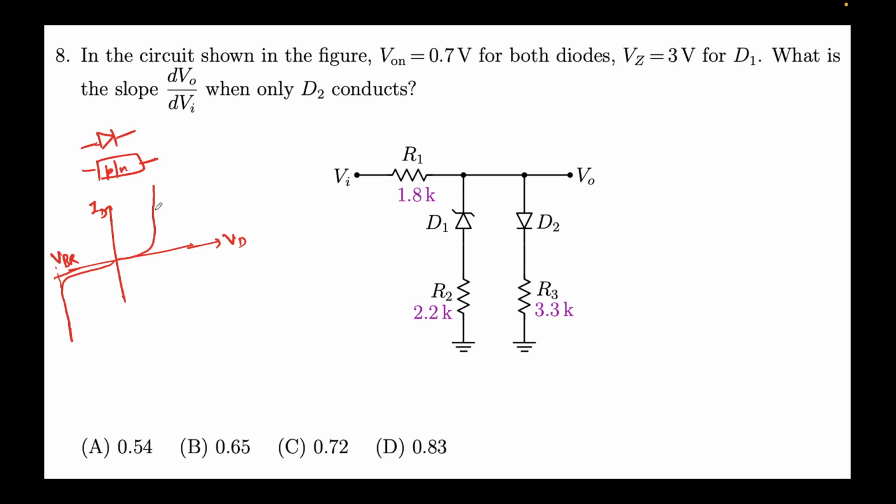And if we take a derivative of this, you can find something called V on, which we are assuming for silicon diodes to be 0.7 volts, right? So when you operate a diode in this region beyond breakdown, this diode is no longer useful. If the breakdown is avalanche type, this diode is useless. However, there are certain diodes based on doping that can be reused.